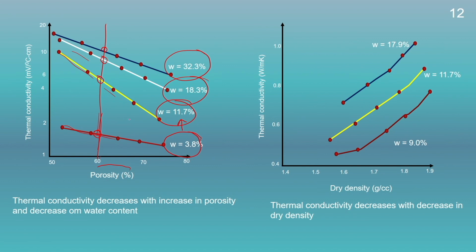With a decrease in the water content, that means more air will occupy the pore space, therefore the thermal conductivity will be less, since air is a poor conductor of heat. Therefore, we could see that with increase in the water content for a given porosity, the thermal conductivity will increase, and with increase in the porosity, the thermal conductivity will decrease.